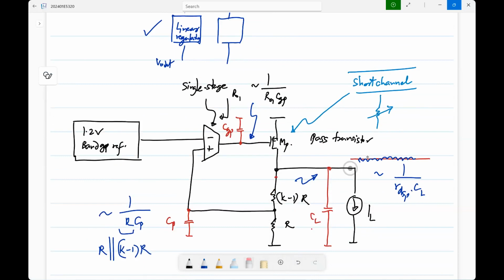Also it's not always clear whether the load will be modeled by a current source or a current source in parallel with some resistance and so on. But anyway, the bottom line is you expect at least 3 poles here, right? Not very high frequency poles, because you don't have very low resistances anywhere, right? So if you just make this, it is likely to be unstable.